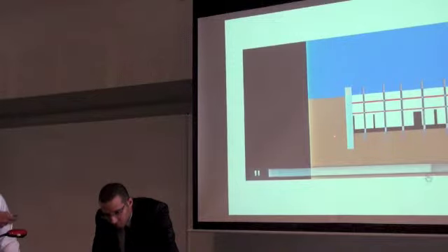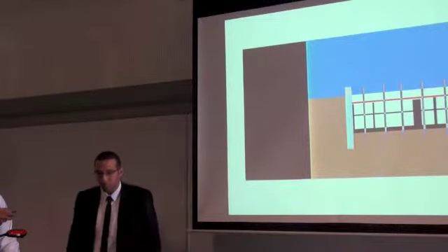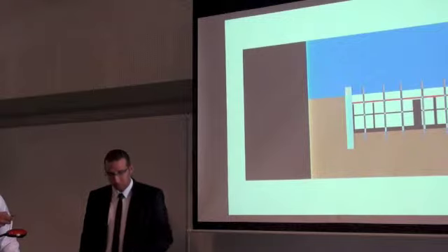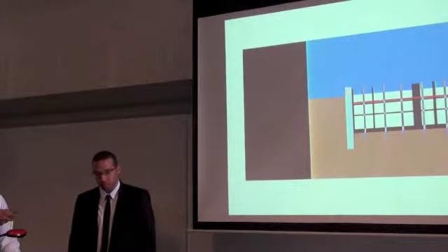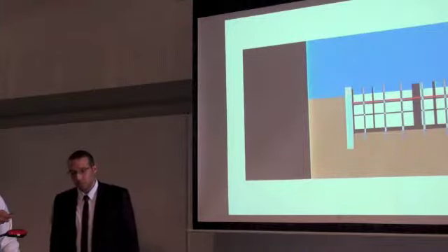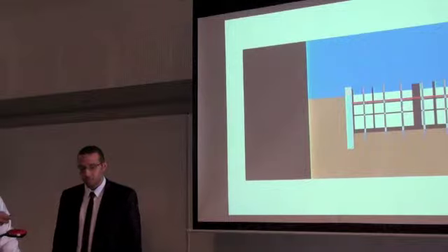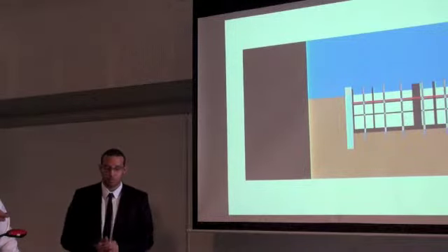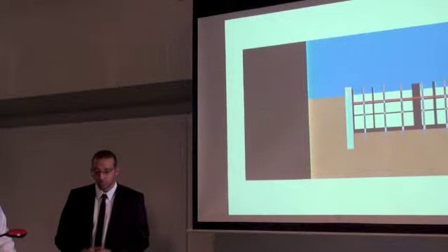Then we construct the foundation, shear walls, columns, and the retaining wall, and remove the water beam when we don't need them anymore. After the water beam has been removed, we will have to cut the piles because they're not needed anymore.